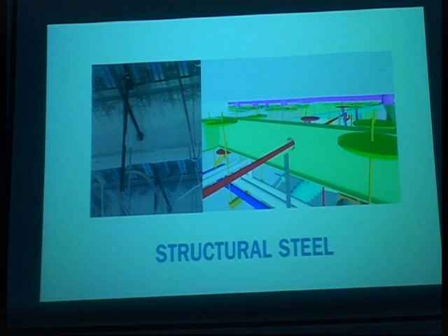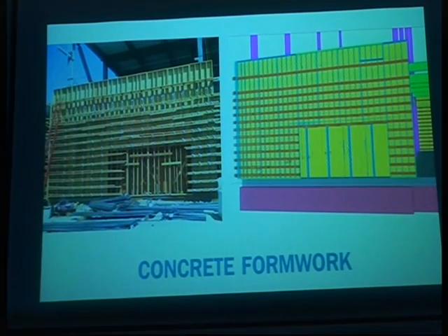The one you saw earlier with the sprinkler system, that was a mistake. This is by design. When we can't move things, then we need to penetrate this beam or joist, but we do make sure that the structural engineer gives their blessing, right? And then we make sure it's built based on what has been approved.